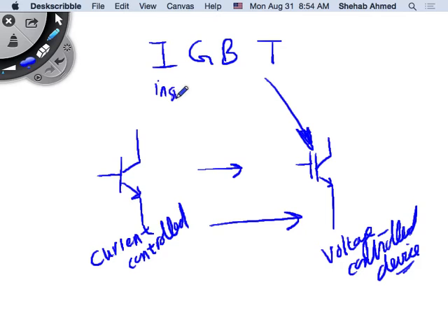Insulated gate bipolar transistor. So it's exactly like the BJT. So it will have the same characteristic, VCE drop across it. Instead of being called a base, right? This will also be a gate, right? And then this gate here will act like a MOSFET's gate exactly. So this gate to emitter voltage is exactly like the gate to source voltage in a MOSFET, right?